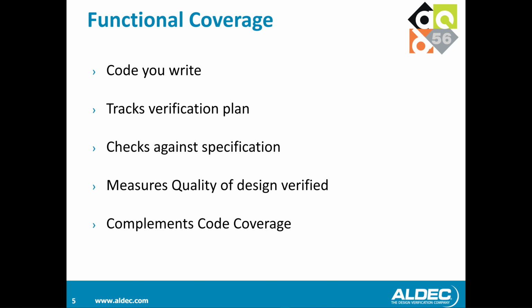For functional coverage, the basic difference is that code coverage only tells you how much of your DUT or design code has been tested, while functional coverage tells you how much of what you intended was really covered. For example, if you have a 5-bit register, there are 32 possible values for the variable. If you randomize and run the simulation without functional coverage, 32 values will possibly be generated, but they might repeat, so you can't say that every value has been covered.